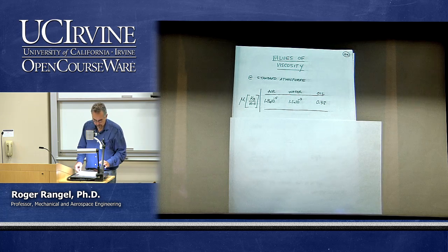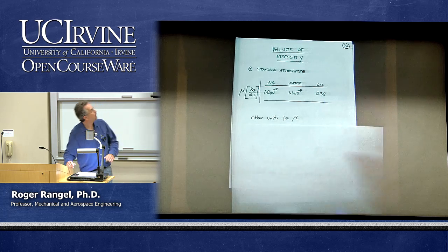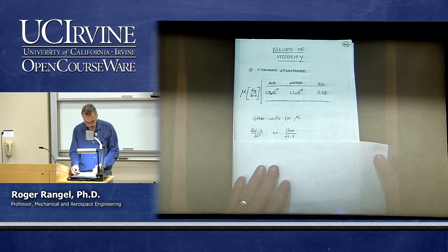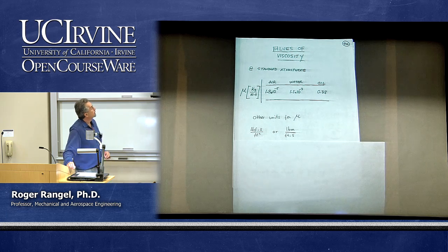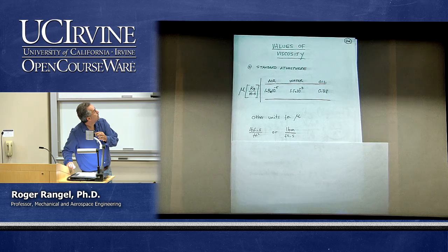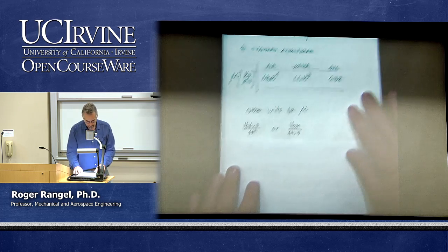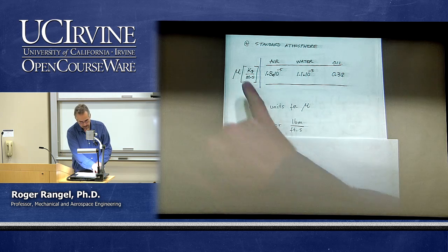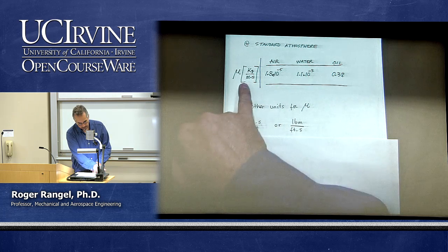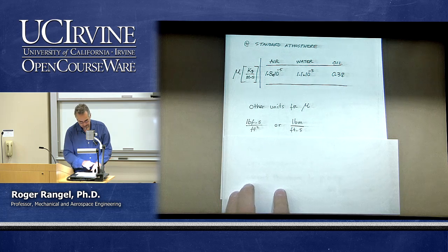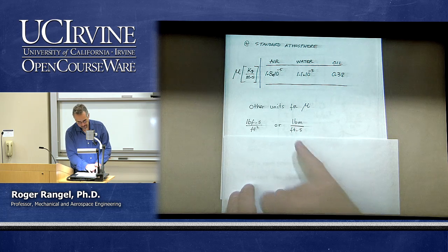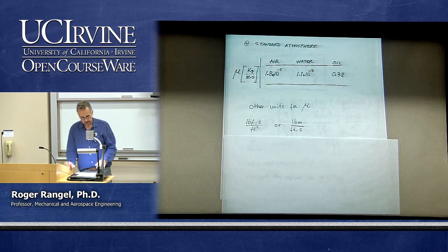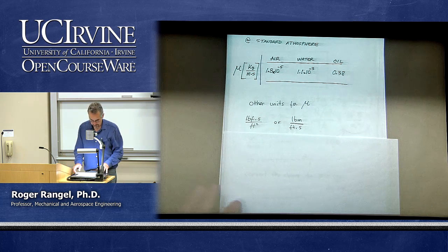It's important for you to be familiar with other units of dynamic viscosity. You might do problems in which you're using English units. Let me blow that up a little bit. If you're dealing with English units, you might encounter viscosities, as you can see, of units of mass over units of length and units of time. For example, pound mass divided by a foot and a second,